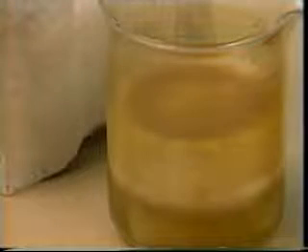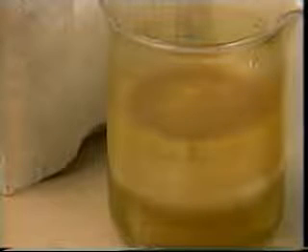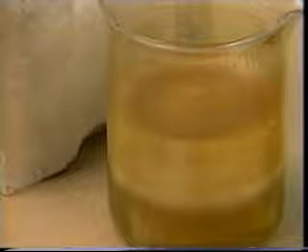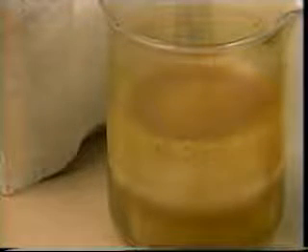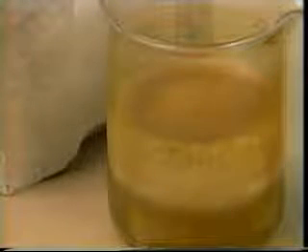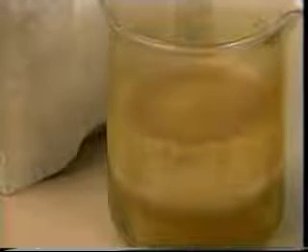At bottom hole pressures, the carbon dioxide and calcium chloride byproducts are usually in solution. As the spent acid returns to the surface, the carbon dioxide may break out of solution and become a gas. This carbon dioxide can serve as an aid in the post-treatment cleanup.